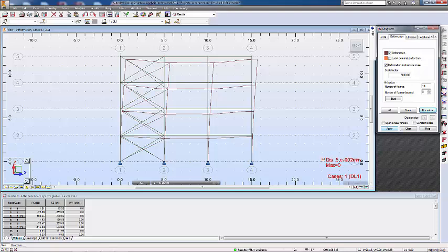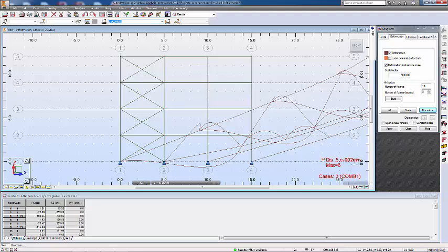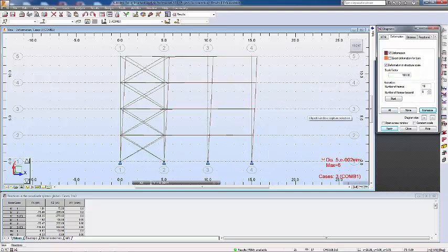So you see, due to the tower here, you get a slightly stronger structure on this side, so you have less deformation, and there is also an unsymmetric deformation due to the tower you built up in here. So this is the only drawback you possibly can see, and then also you can see the combined effect. Of course, this 5000 is too much, so let's maybe change to 100 to allow you to see this part. So this is a pretty nice structure, stiff enough to withstand the loading.